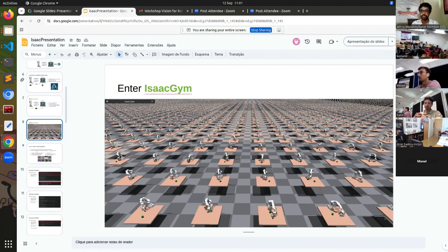There's also other types of manipulators like suction cups. We could have used a suction cup, but this involves touching the surface, right? And this surface is where the painting is, and the painting is very sensitive to scratches and to losing its natural color. So we want to avoid actually putting any rubber material and constant suction cups to prevent this. And there's of course other dexterous manipulators we can use that have more degrees of freedom.